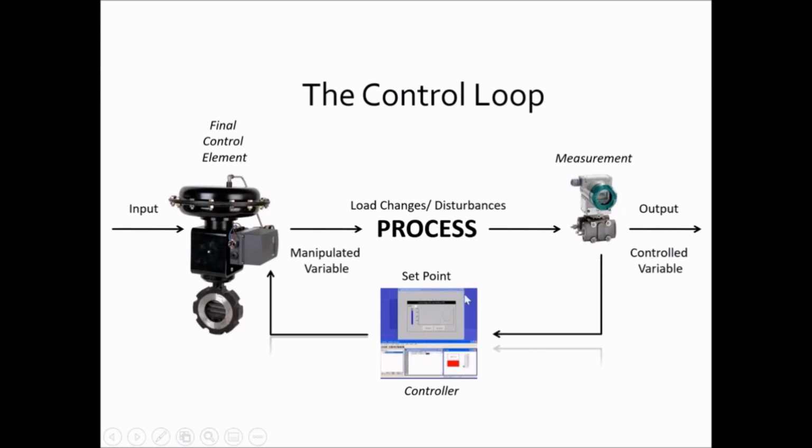You have your PLC, your DVC, and then your positioner, and your control valve is adjusting and trying to keep the measurement device happy or in balance. The control valve will do whatever it needs to do to make sure this holds tight at 40 psi or 50 GPM or whatever we're trying to measure.